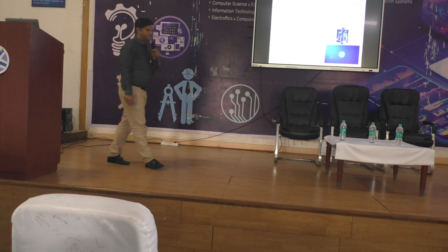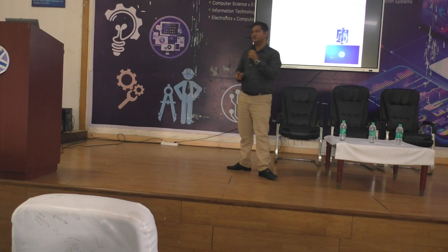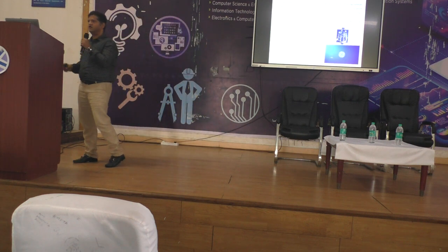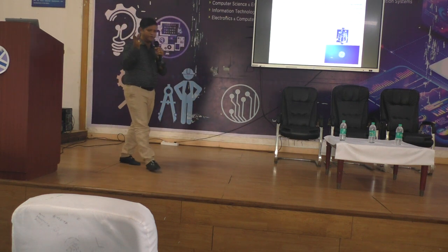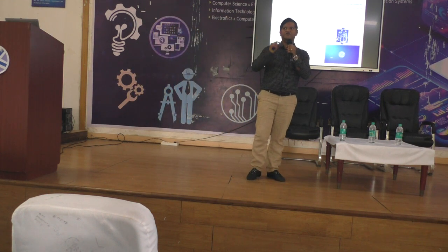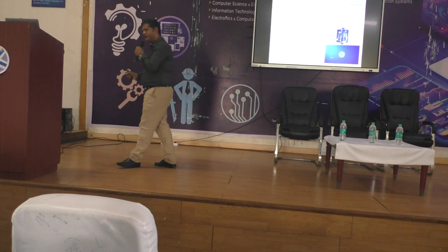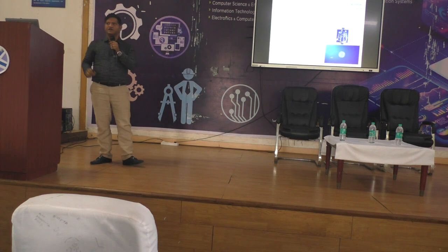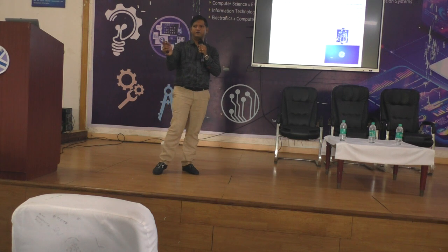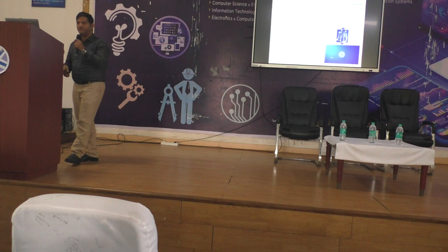That means once you make the model and rectify your STL file for errors, and before slicing, once you optimize your orientation and process parameters, then you slice it and give that slice information to the additive manufacturing system, and your job is done. It is the machine's job to complete the component. There is no need for you to interfere in between.